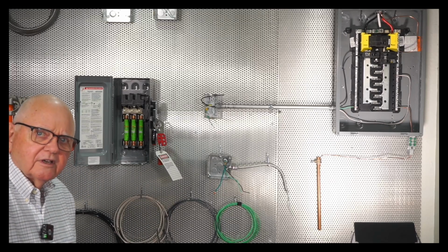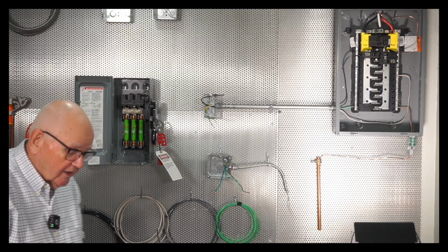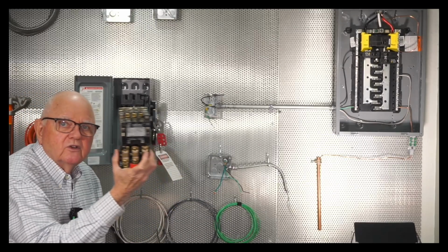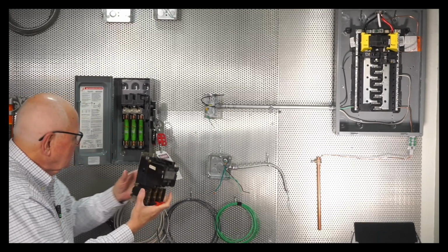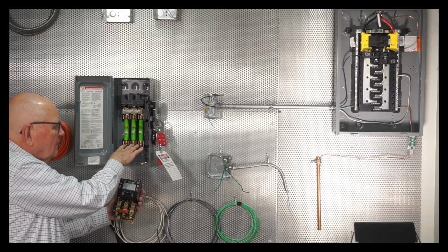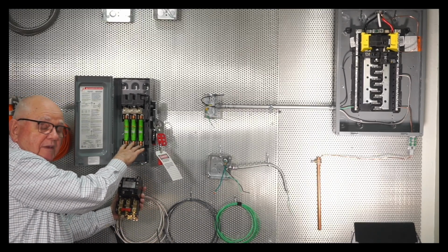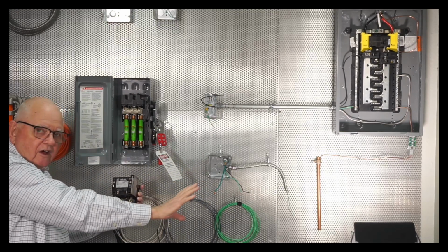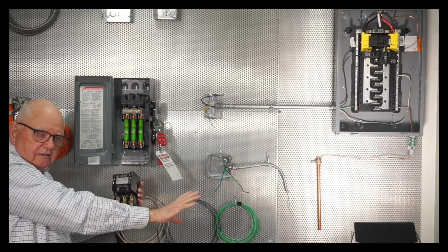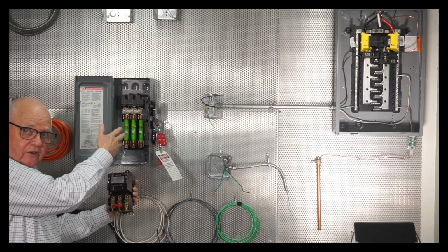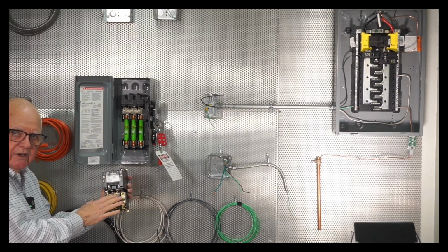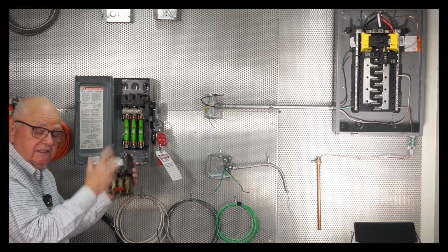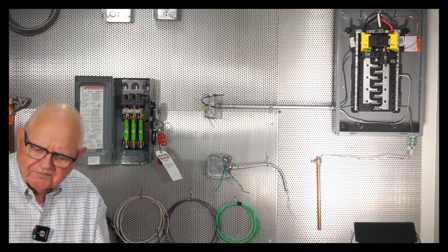Now, it's also important to understand that when I talk about a motor branch circuit, I'm also including my motor starter. So any accessories that I would have from the bottom of these fuses, through the conductors, through this motor starter and out to my motor, that's all my branch circuit then. And it's a 30 amp branch circuit because I have 30 amp fuses. Overload protection, we know, is supplied by the overload in the motor starter. And of course, that is Article 430.